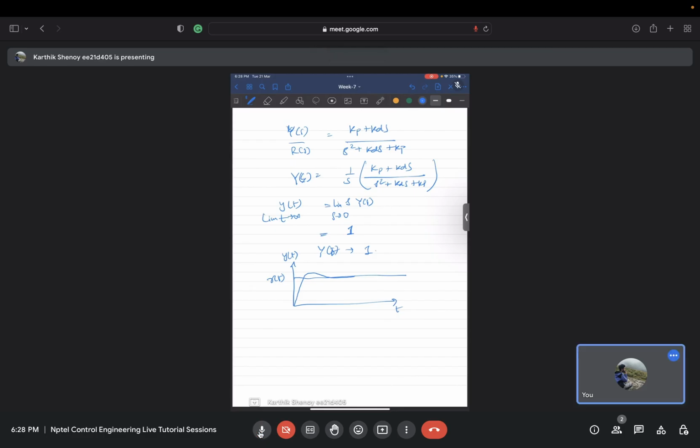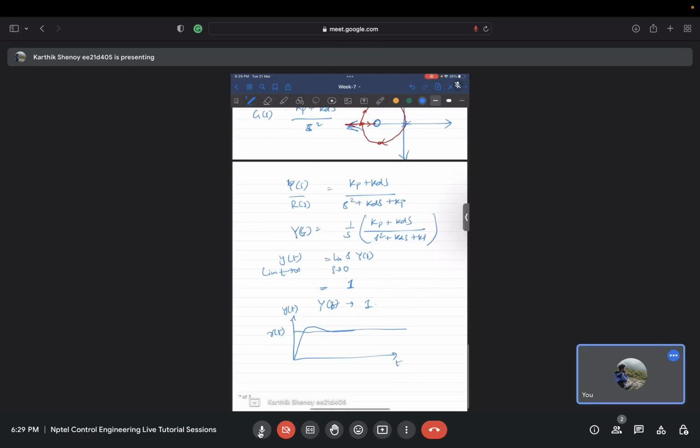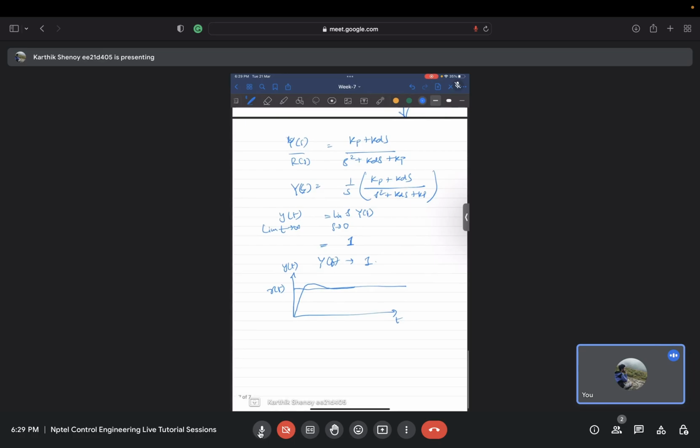Okay, so that's why I don't need an integrator here. Unnecessarily, why add an integrator? Because there are problems if you add an integrator. It will lose stability. It can reduce the stability of the system. It can cause something called integral wind-up, which we'll see as an example later, and things like that. Okay, so we'll look at a different system.